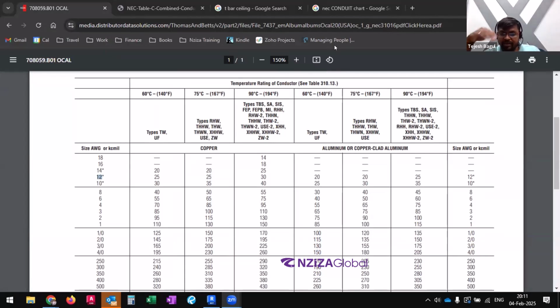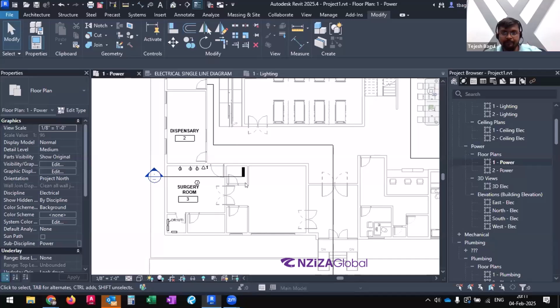But make sure you properly explode all of the blocks from AutoCAD before bringing it into Revit, just because the interface of Revit and AutoCAD do not sync one-to-one, and then there might be some blown out things that you might be seeing on the Revit drafting plan. All right. I will come back to the AutoCAD schematics in a moment, Grace. Give me a moment.